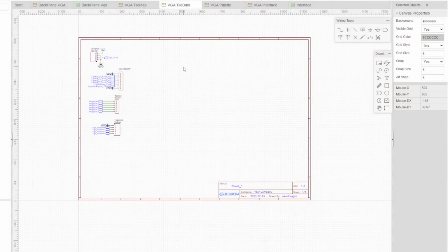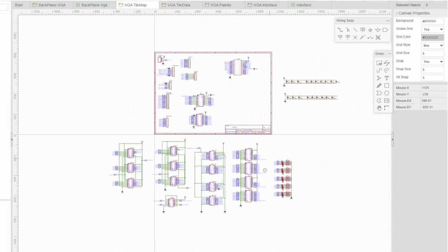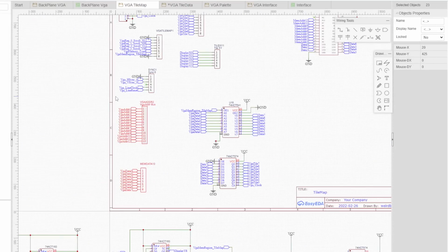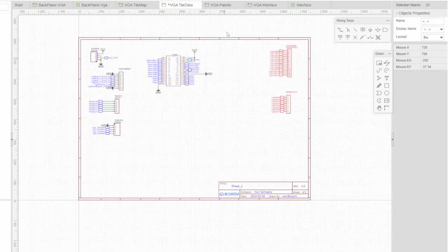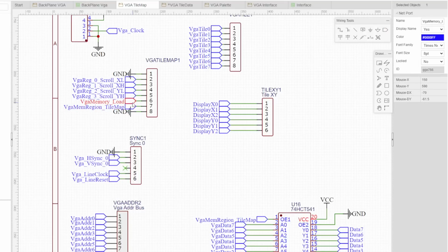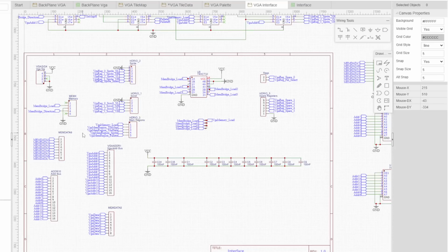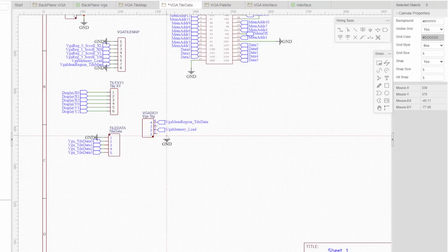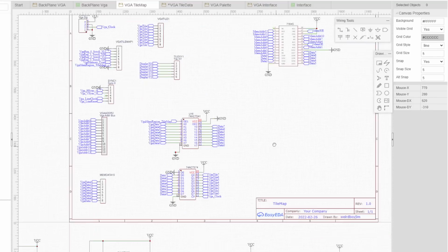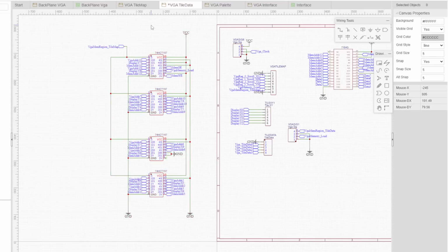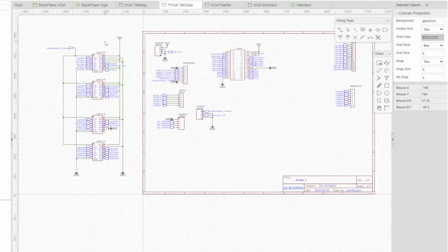The tile data circuit is going to be heavily based on the tile map. Same 64 kilobit memory chip, address bus and data. Now we won't want the same memory region line, but we will want the load line. We want the 157s to mediate the incoming address.